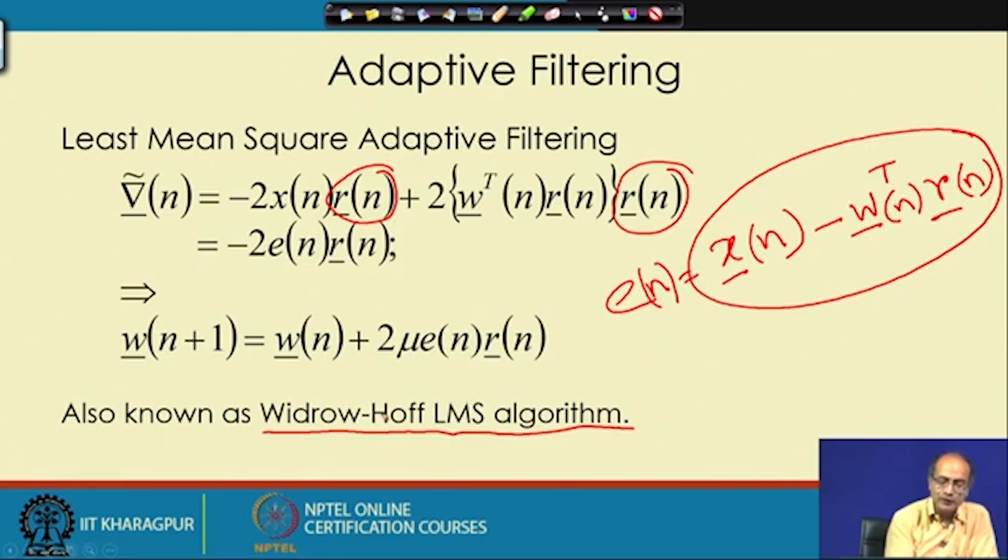This simple equation we can use to update the weights, and as we keep on updating the weights, it will keep changing and latch onto the process. If the process is changing, because the signals are non-stationary, it will respond to that change, and by updating the weights it will always try to remain an optimal filter.